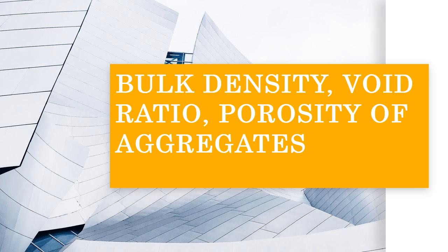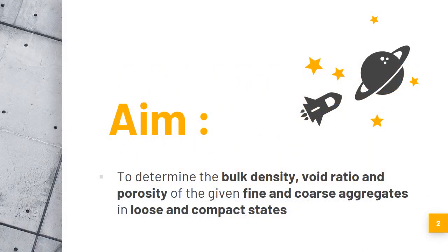The name of this experiment is bulk density, void ratio, and porosity of aggregates. The aim of this experiment is to find the bulk density, void ratio, and porosity of the given fine and coarse aggregates in both loose and compact states.